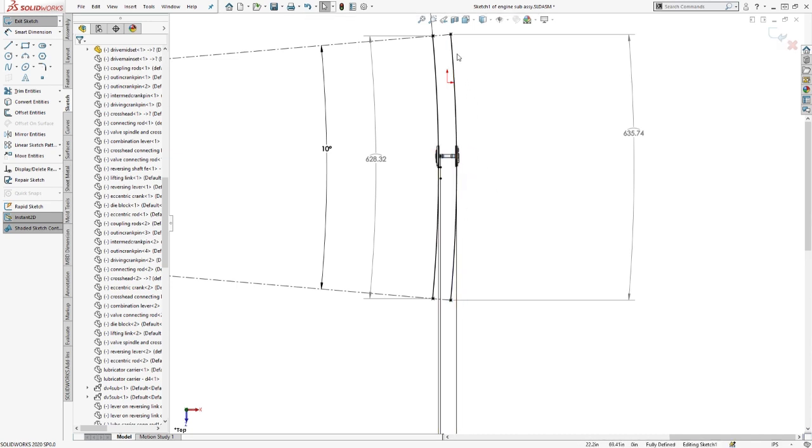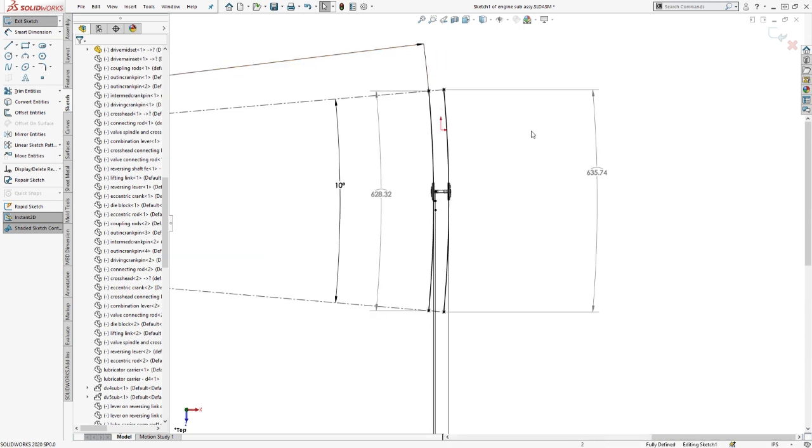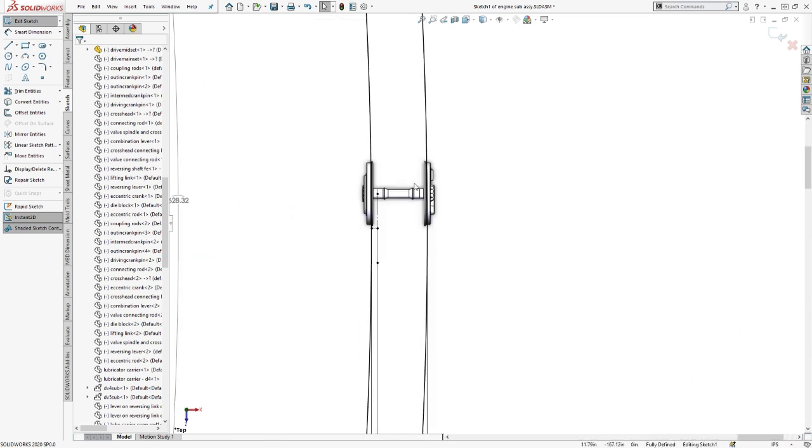So if this only travels 628, you see it's coming up short. And the further around we go, 20 degrees, 30 degrees, the worse it's going to get. The tighter this radius, the worse it's going to get. You're putting a lot of stress on your axle, and eventually the tire is going to slip.